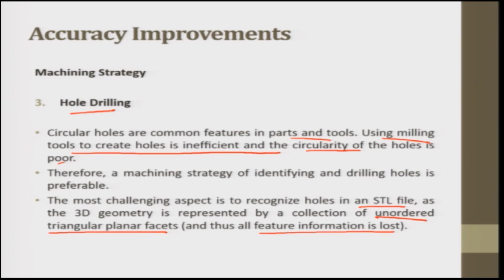Now, people have used algorithms in recognition of the holes, because the hole and the surface have a closed loop here. So, these algorithms, which are made up of sharp edges from the model, are used to determine the holes. Now, the closed loops may not necessarily be the intersection curves between the holes on the surface. So, a series of hole checking rules are used to remove the loops that do not correspond to the drill holes.